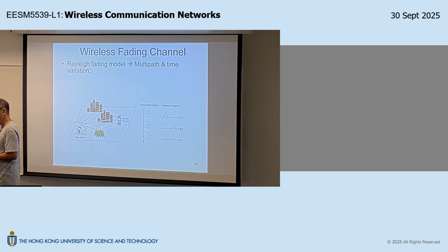So even for a laser, the transmitted beam is not absolutely parallel. So for a non-zero solid angle, the surface area must scale like order d squared, and therefore you will have the inverse square law. So it has nothing to do with your isotropic source or whatever. Even if you do beamforming at the transmitter, you still cannot get away from this inverse square dilution of energy. Is that okay? So this is path loss.